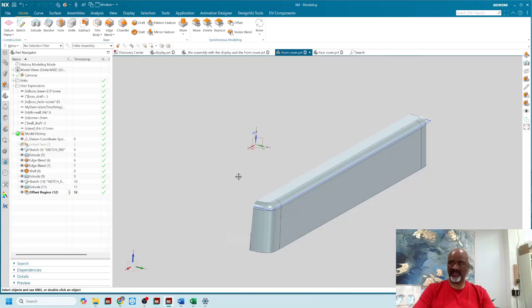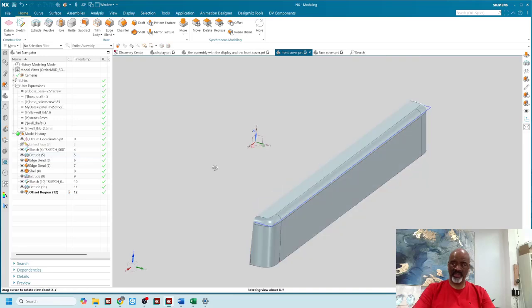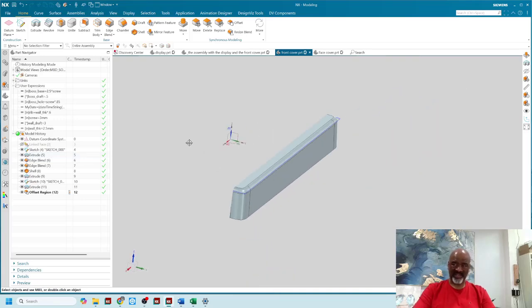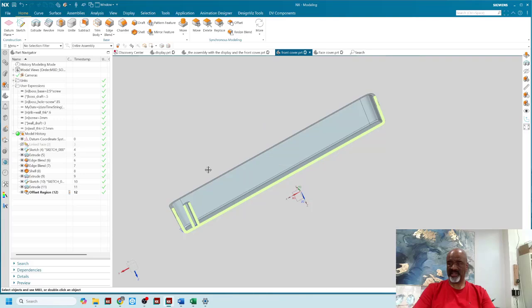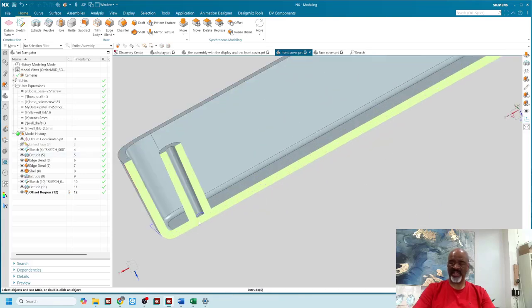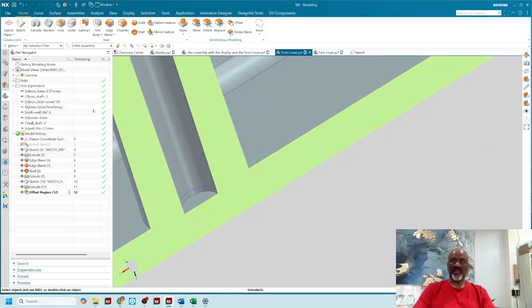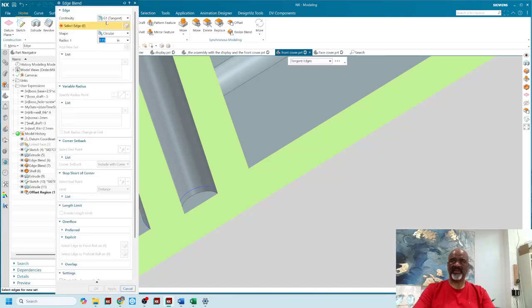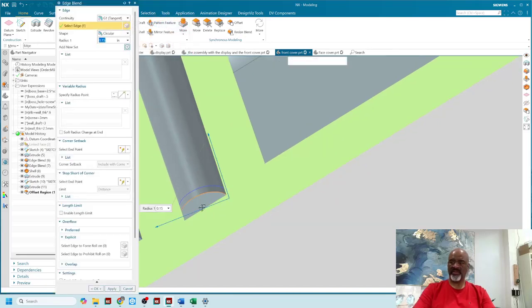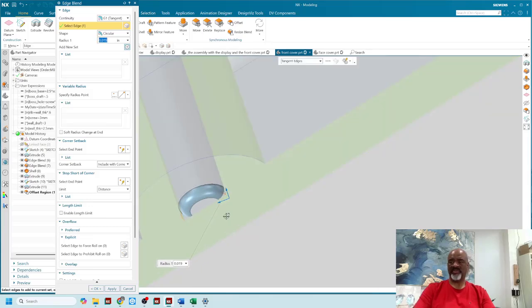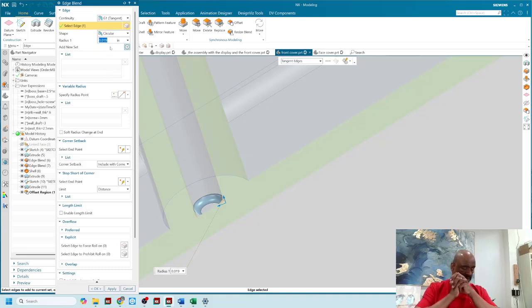It really isn't. By definition, the A surface is a surface that is going to be cosmetic. It's going to be seen. It's not necessarily a mathematical designation, A and B. Another thing I should do is put blends in here to have the material flow more evenly, more smoothly, and that is going to be a percentage of the overall wall thickness as well.